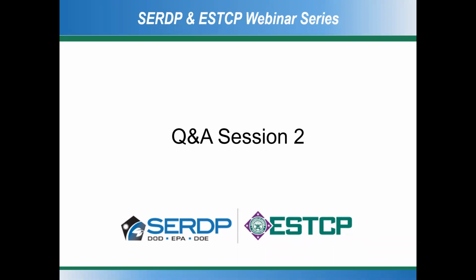Yes, we are. So we're also looking at pure electrochemical treatment. And I think one of my slides actually said electrochemical oxidation can virtually degrade any organic contaminant. And to my knowledge, there is no organic contaminant that has been shown to be stable in these systems.